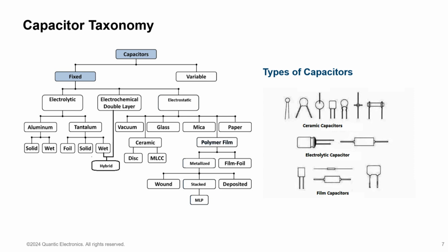Electrolytic capacitors utilize a high surface area anode separated by an electrically formed insulation layer along with a conductive electrolyte to effectively create a very large surface, very large plate with a very thin layer of separation. That means high cap density. The anode can consist of sintered porous metal or roughened etched foil. The cathode remains electrically connected to the electrolyte solution.